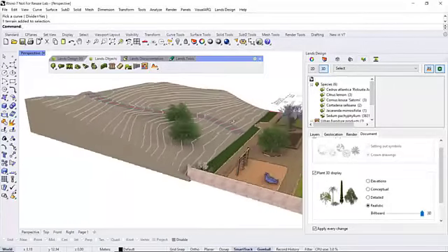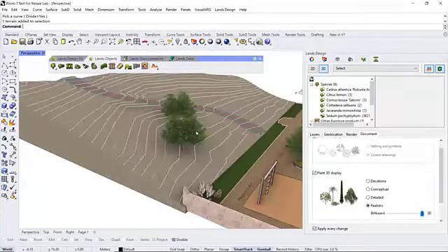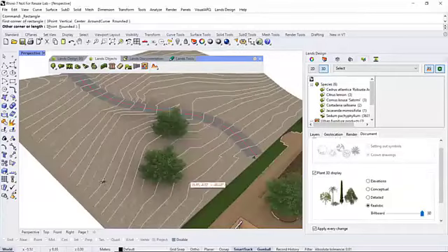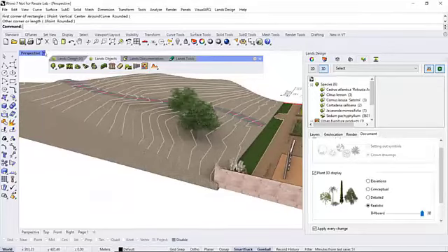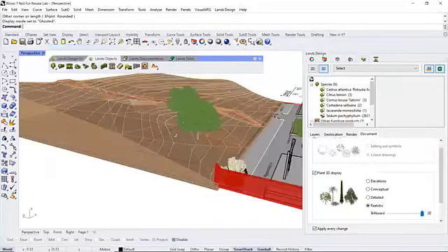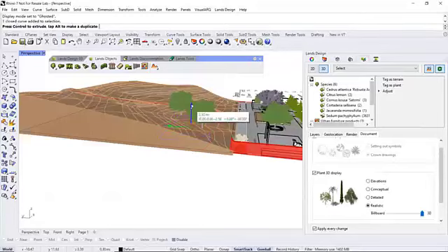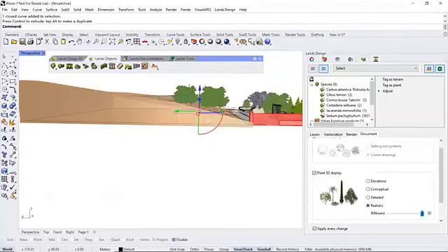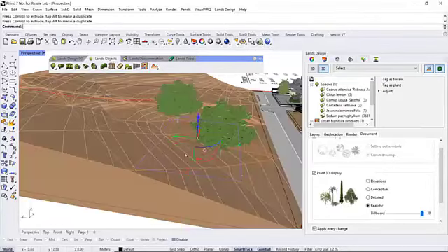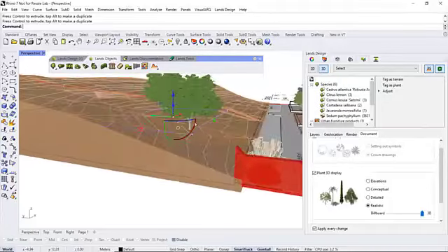All right, and well, in a similar way, if we want to flatten some area over here, we can draw, for example, the boundary of this area. Let me show this in ghosted so you can see where my rectangle is, and I'm going to elevate it a little bit so we've got part of it inside the terrain and part of it outside.